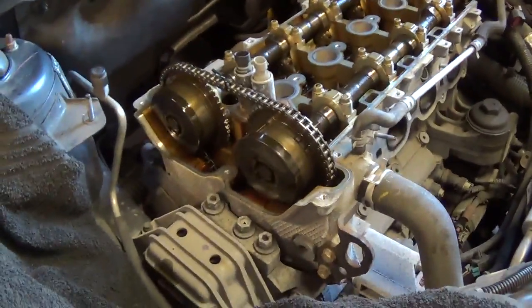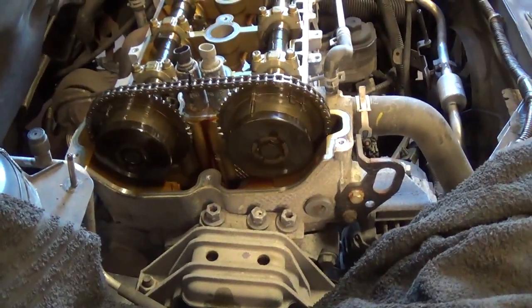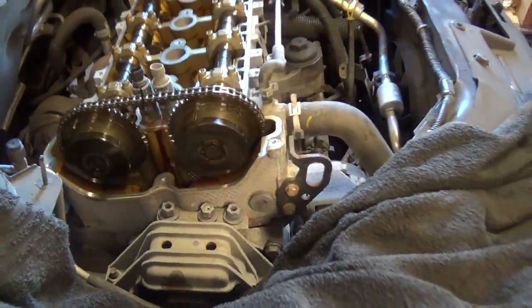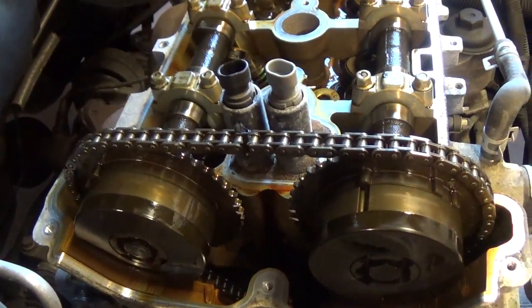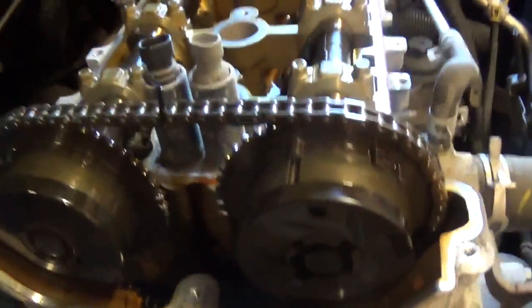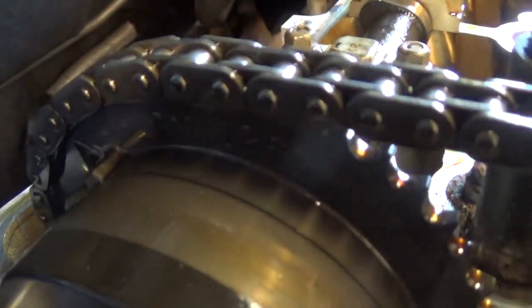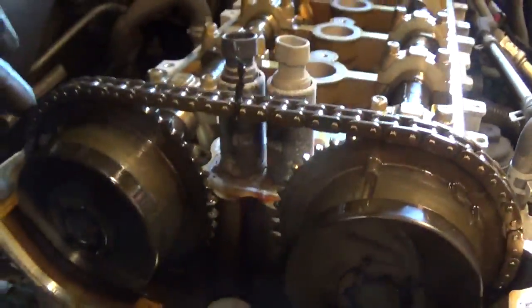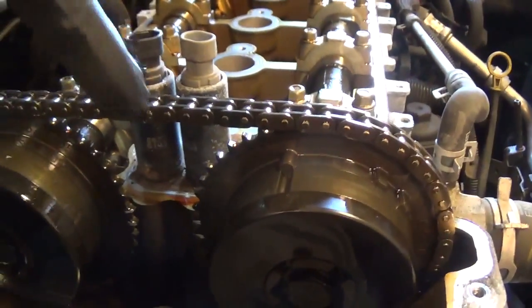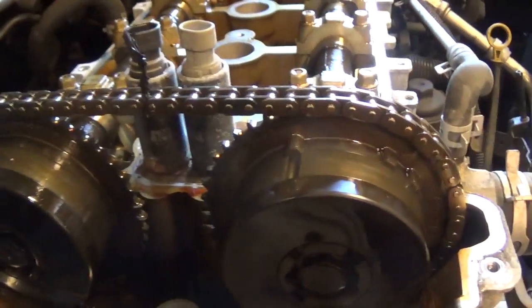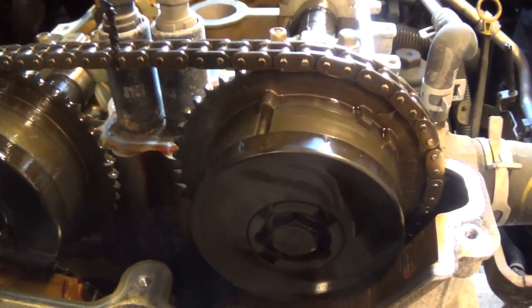Valve cover, and to get the timing lined up here before we take the camshafts out, you need to park the number 1 cylinder TDC exhaust stroke. So that's the factory procedure, so I'm going to follow that. And you can see here there are little arrows at 2 o'clock there, and about 10 o'clock right there. And you can count links. There are 15 links from mark to mark. I got a little zip tie here right in between, so we can, the more places you mark, the better.